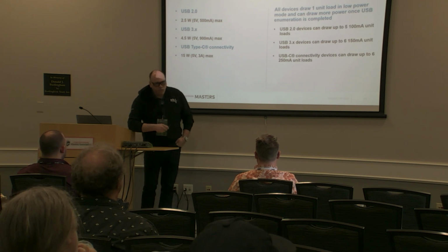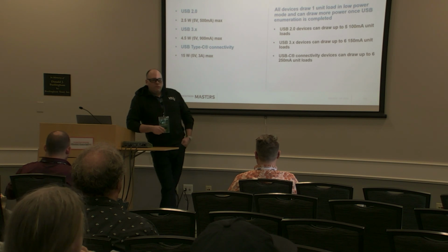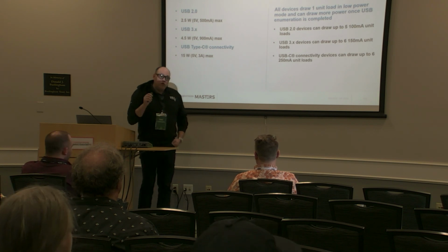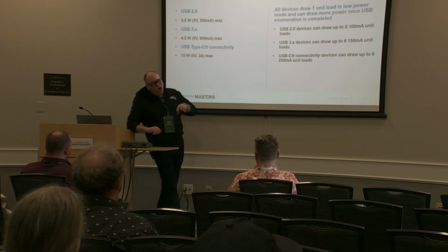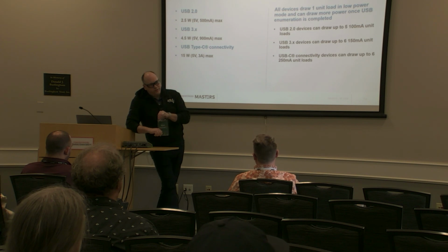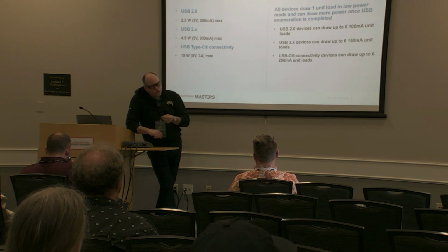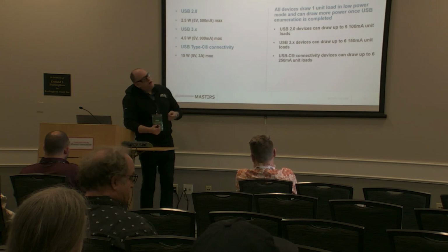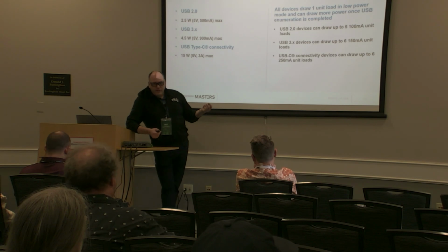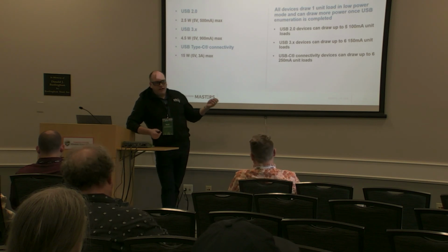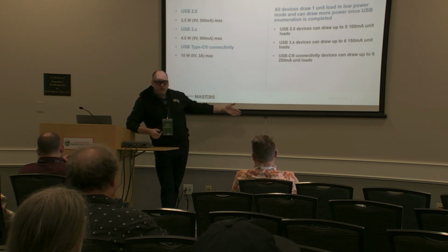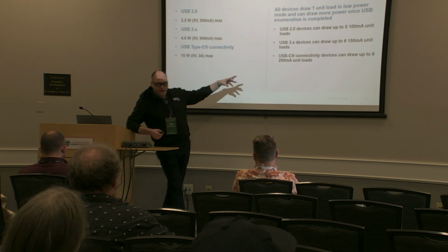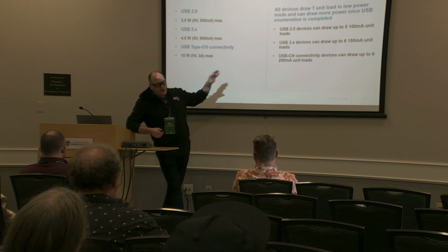Doesn't the hub provide its own power, like a power supply? Yes, but we're talking about what the host controller on that hub is actually going to do. If you have one that will give it more power, then you can get it, but the host controller is only going to give it so much. So if you plug a passive hub into a port, then all it's got is what's available on the root host controller. Will the hub take one of those power units? It will, and we'll talk about that.